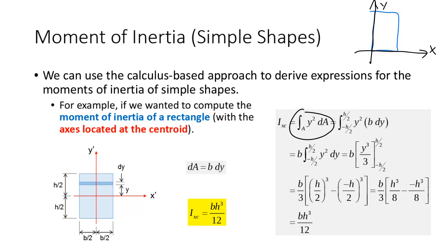See, the formula for the moment of inertia is the integral of y squared dA, so it is dependent upon where your coordinate system is. And so maybe one of the questions you might ask is, where is the most appropriate spot to place that coordinate system? I'd argue for most practical applications, the centroid is where you would place it. And so we have to talk about how to approach that for a generic problem.